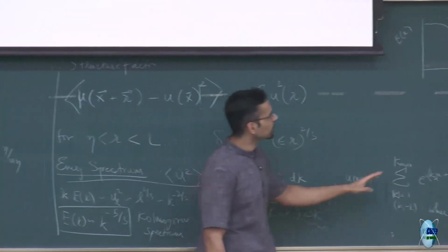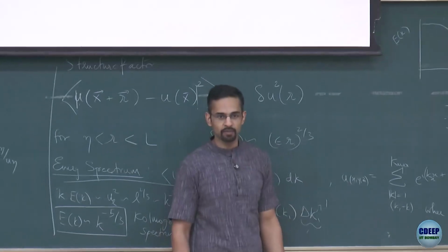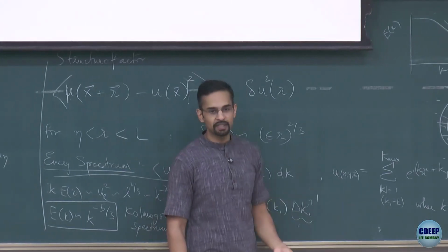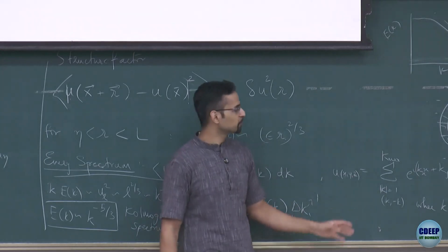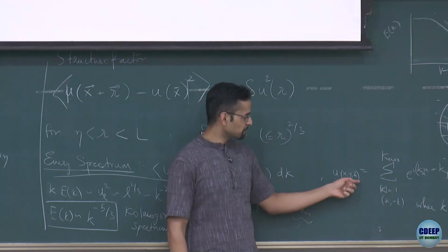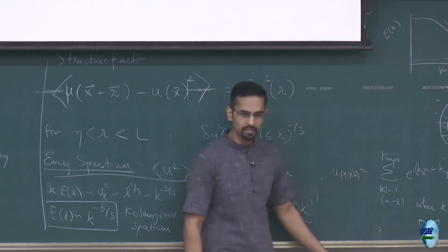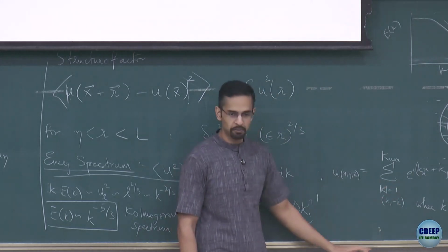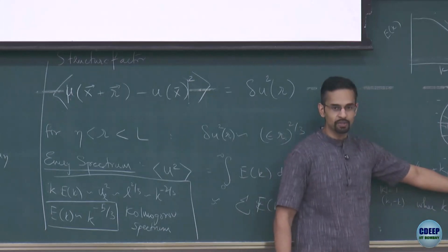So now if I want to cook up a stochastic random field which mimics a turbulent flow, one of the basic things I'll want to do, if I'm interested in spatial structures and spatial information, is to put in this Kolmogorov spectra. All that means is when I'm making my velocity field, I can create it using a sum of sines and cosines, or exponential Fourier modes. And then I just have to take care of what the amplitudes of the different modes are.